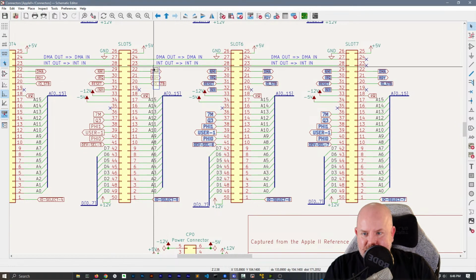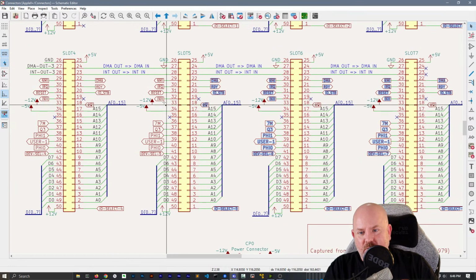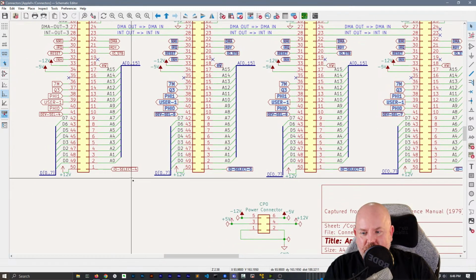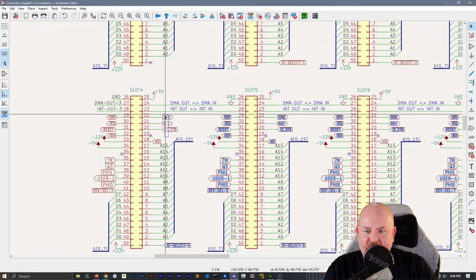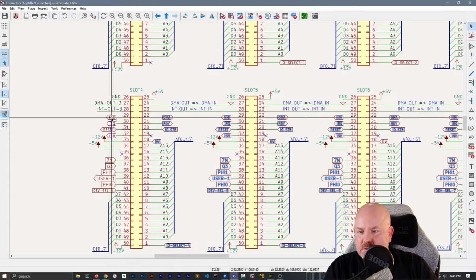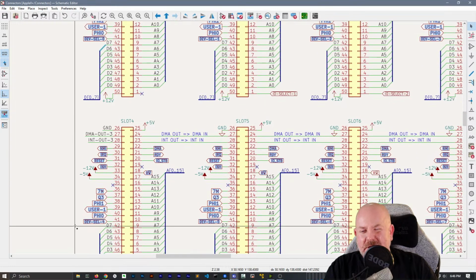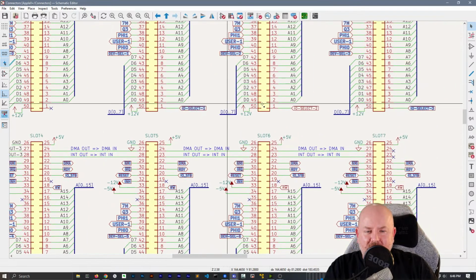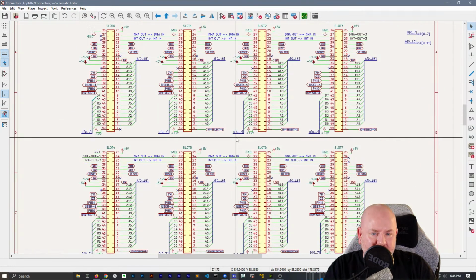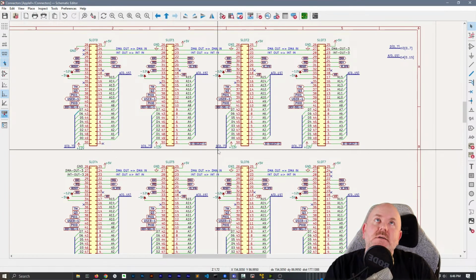When you're trying to turn a board on, that is not a good time to find out that you shorted the power rail to an output of the microcontroller. Although, I think one of the flags is power rail connected to tri-state.